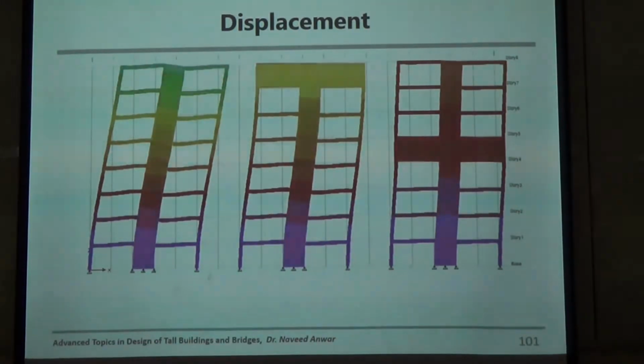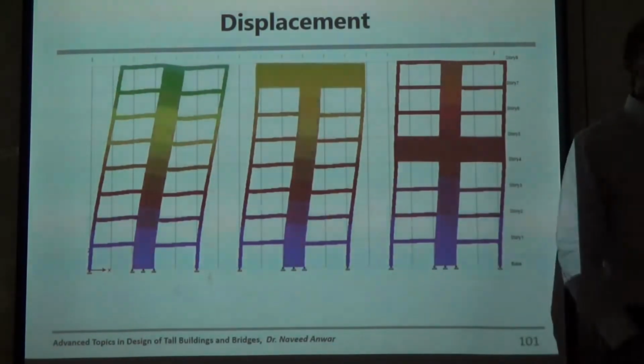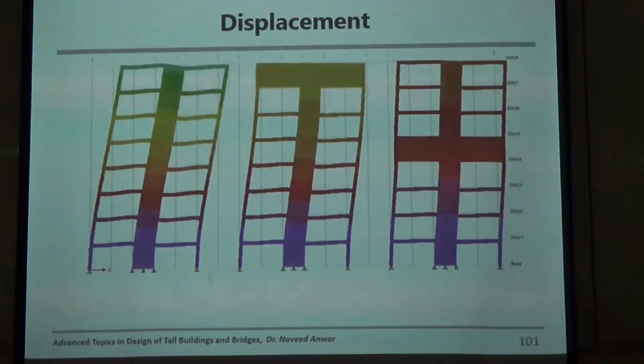Which floors are available? Normally, we are looking for floors which have services. Normally, they put the generators and AC power plants or something like that somewhere in the middle of the building. And you are looking for that floor. And then we try to put the outriggers on the services floor. Or we talk to the architect, but the problem is some buildings don't have service floors, like residential buildings. So then you cannot find an outrigger location. Very difficult. So even though we know structurally which is the best location, you cannot actually use it because of the architectural constraints.